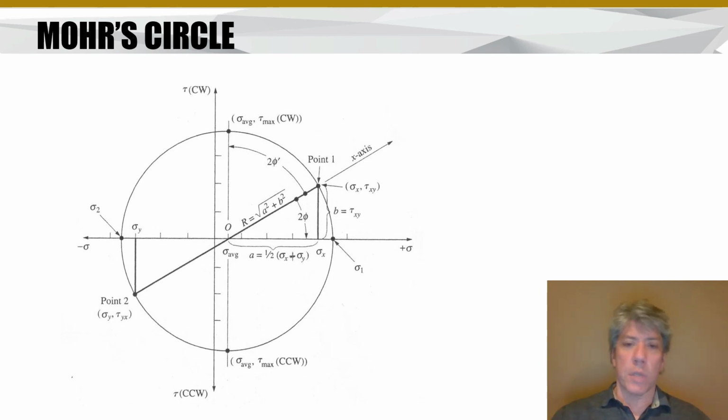The principal stresses are also very important because if you're dealing with a brittle material, you need to know the maximum magnitude of normal stress and the angle at which it occurs.